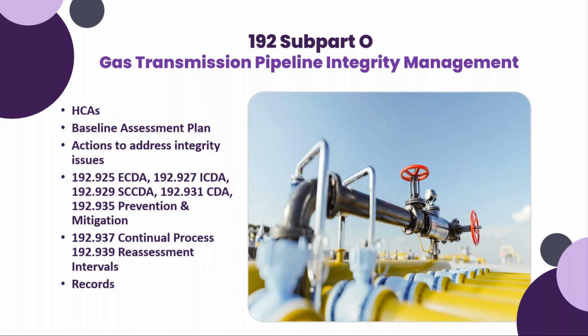Subpart O. We talked about the high consequence areas, the baseline, the actions, the DA, ECDA, ICDA, SCCDA, and of course, confirmatory direct assessment, where you only have to do one survey once you get the others completed. And then the prevention and mitigation. And where is direct assessment used? Primarily on unpiggable systems, okay?